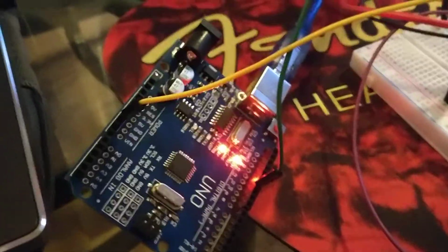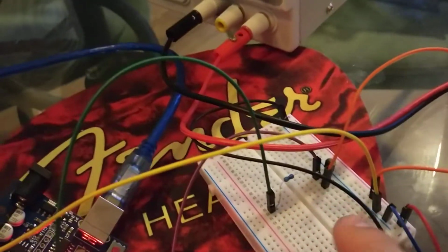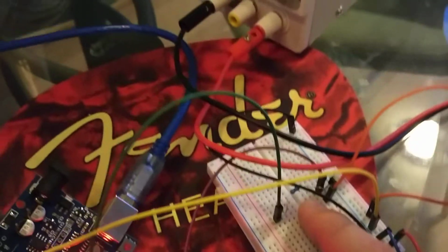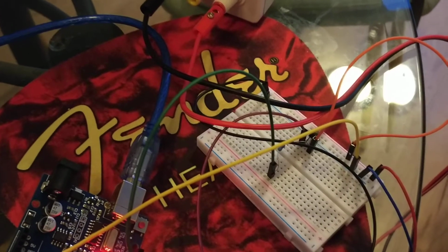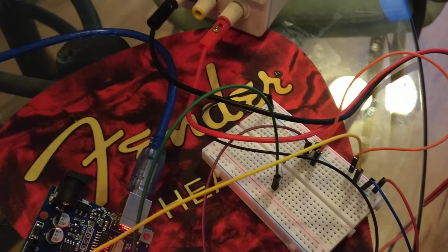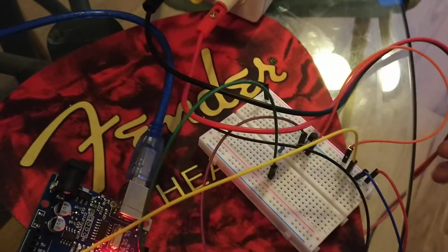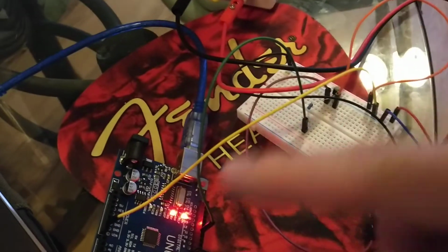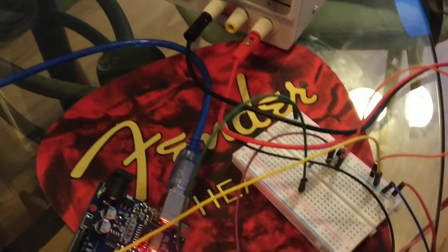Okay, it's already uploaded. We're going to go here to the proto board. Now, what I have going on here is you can see that there is a connector coming in from pin 11, and that is coming over here. Then there's going to be a resistor in line. The resistor, I don't know if it's necessary. This transistor, I found that on the spec, I found that it was rated at, I think, like 5 milliamps. So I put the resistor in line to calculate for that 5 milliamps. And then we have the ground. We do need the ground for the reference for the Arduino, otherwise it's not going to work.